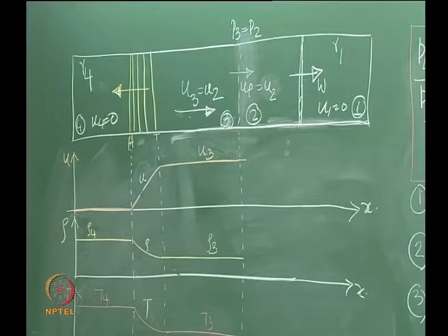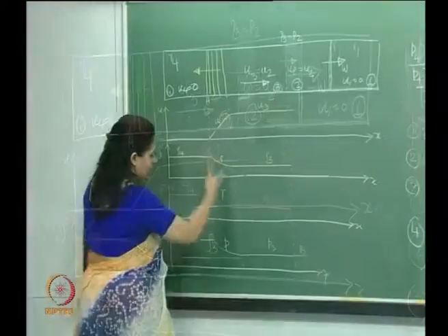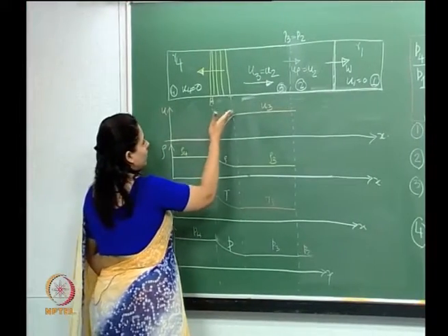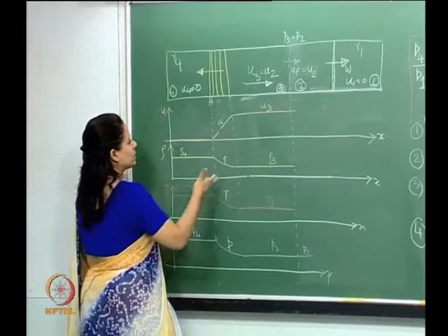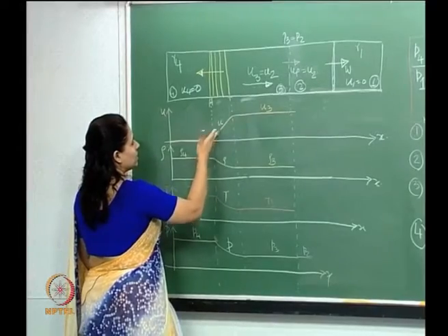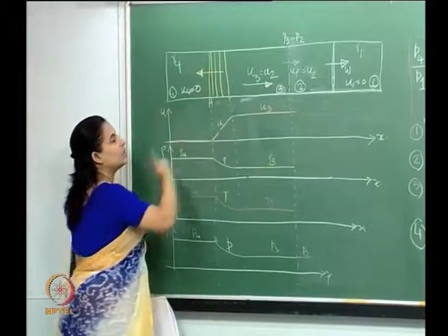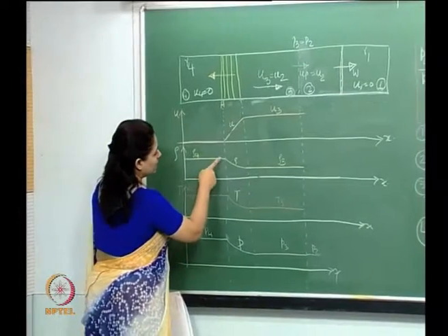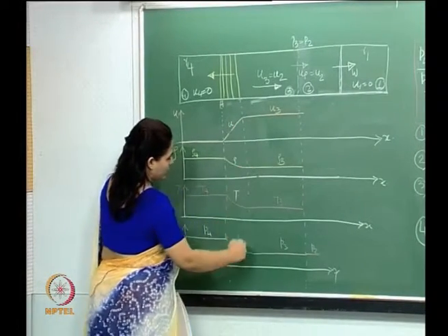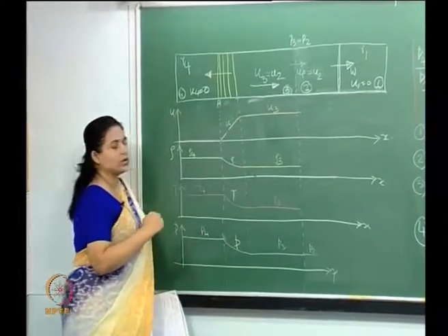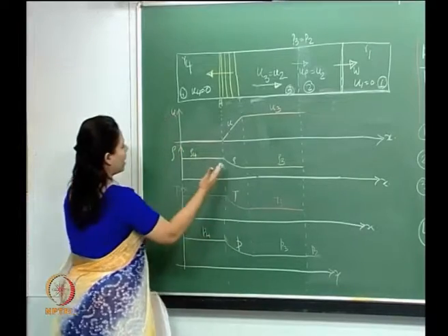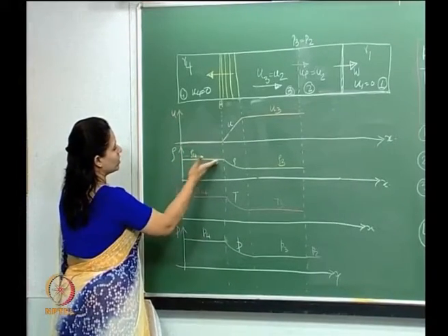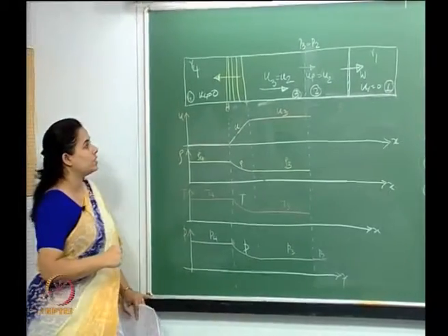And that is something you can see represented in the properties. As the velocity decreases linearly within the expansion fan, it is an isentropic process, and the density, temperature, and pressure all increase in a nonlinear manner, and then reach constant values in the quiescent region.